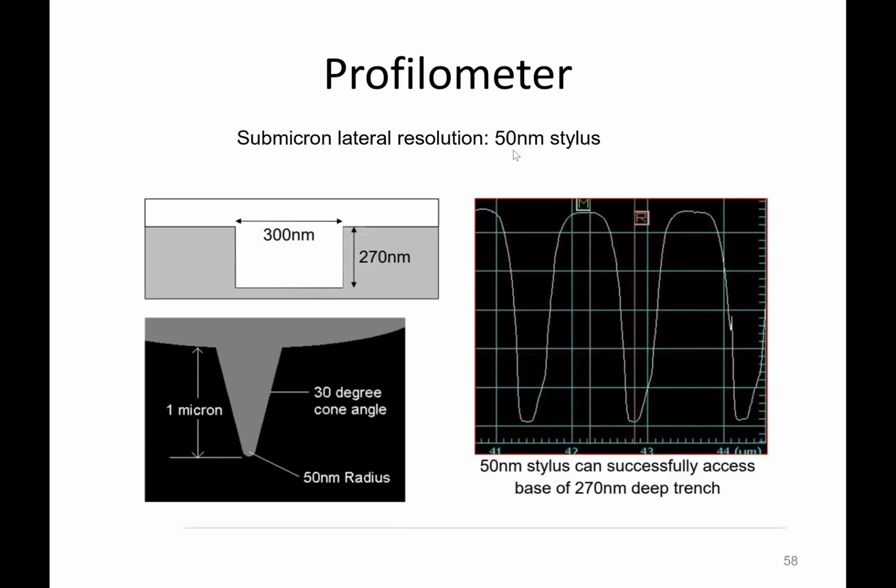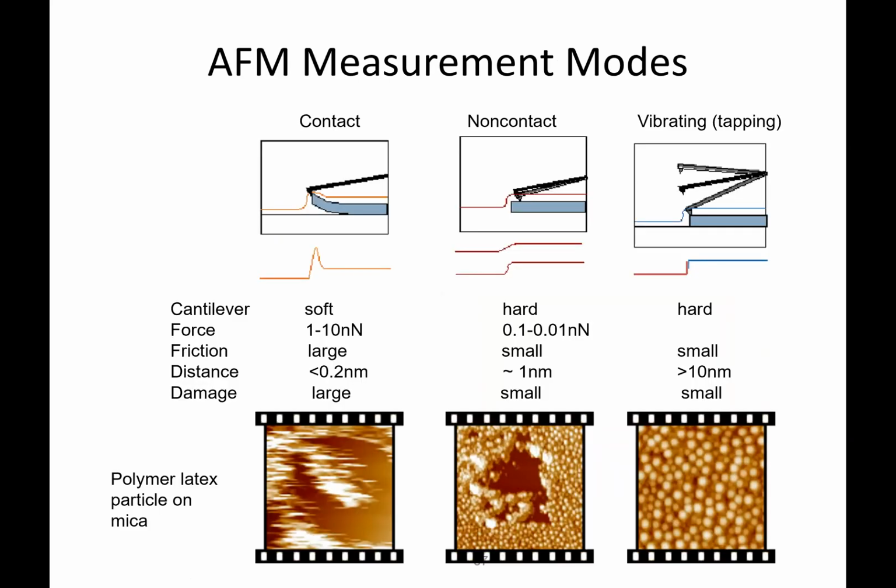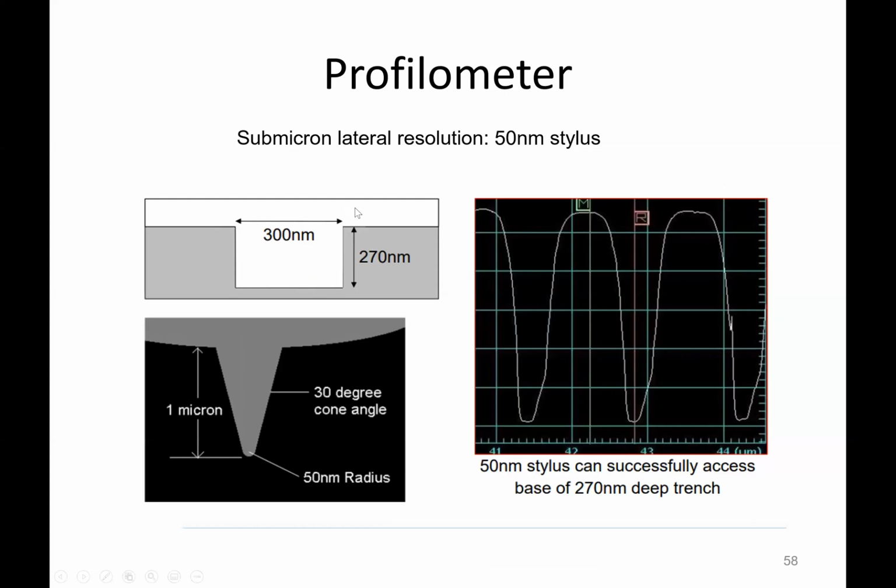And also the profilometer. This is the atomic scale, but for practical use in industry to measure some step height, not nanoscale features but sub-micron, these large size features, the profilometer can be used. In this case, having this scanning with large features compared to the previous atomic force microscope tip, this has a very large tip. But still, 300 nanometer types of things can be measured.